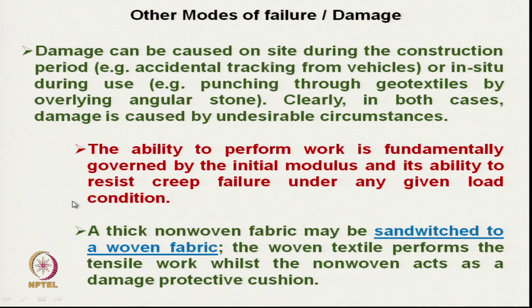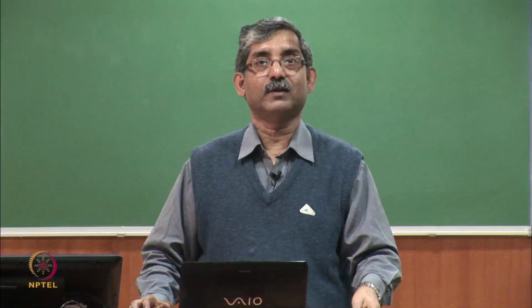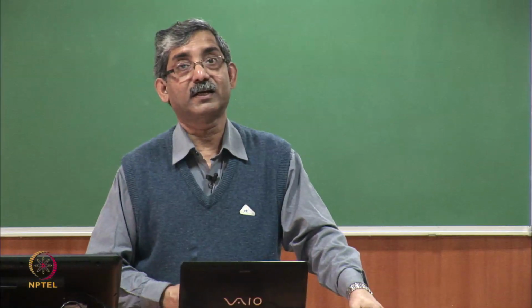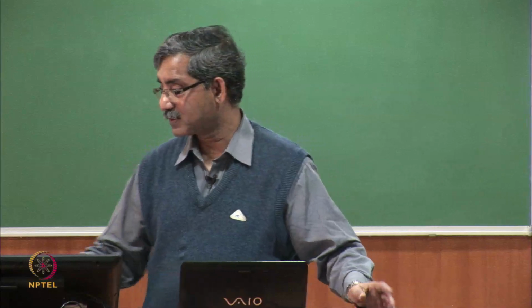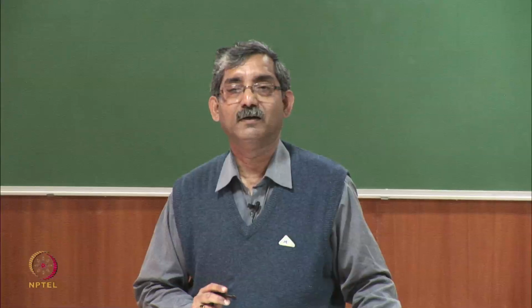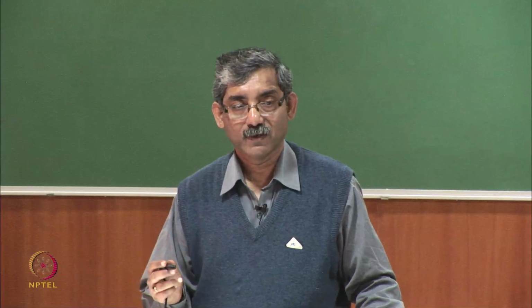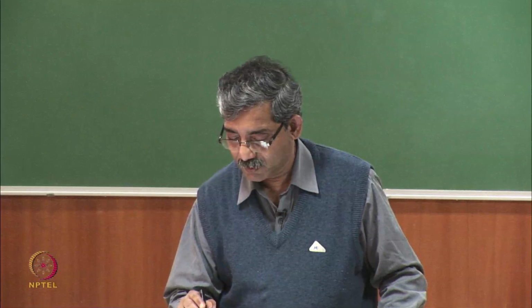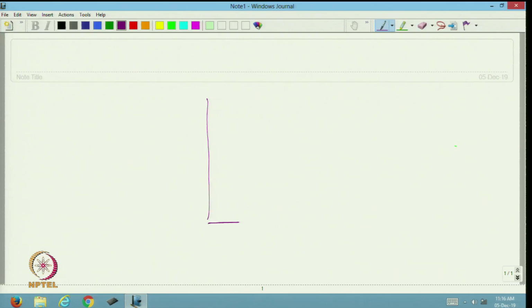That means, we must have clear idea about the initial modulus and its creep. Now, let us see the importance of initial modulus. The ultimate strength is not that important for geotextile construction, it is the initial modulus. So, initial modulus means